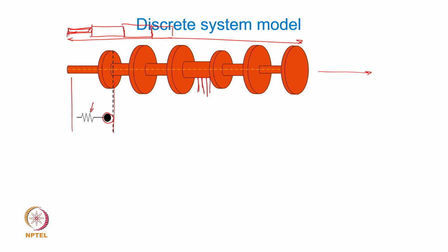Now, if you make the segment as small as possible, the approximation involved in lumping the mass property, which is actually distributed throughout the length, to one end of the segment will get reduced if you segmentalize into several segments. So you imagine that the segment is small enough not to let that segmentalization affect your eigenvalue estimation.